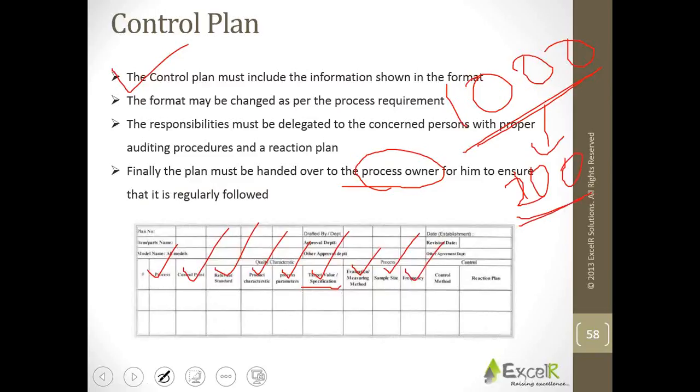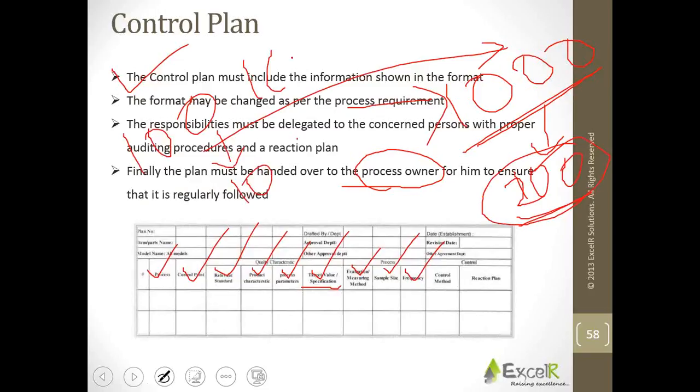Frequency. Suppose in a day there are 1000, will you audit 200 samples at the end of the day? Or will you say that while these iPhones are manufactured, say in the first hour there are 100 manufactured, out of this 10 immediately I'll do it. In the second hour, people manufacture another 100, so immediately I'll pick another 10. In this way, for the entire 8, 9, 10 hours, I'm going to continuously take 10 iPhones and start auditing that. That is called frequency. You define the frequency.